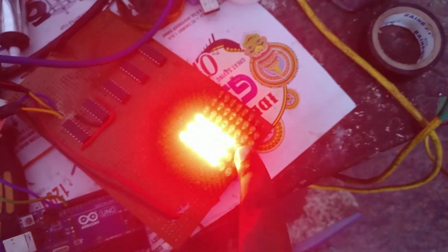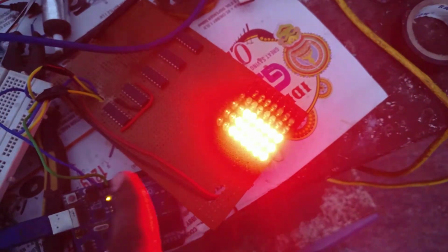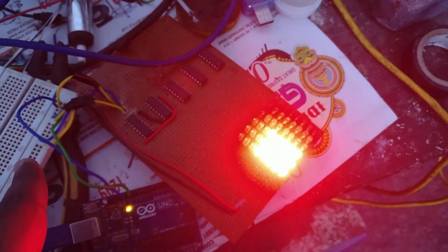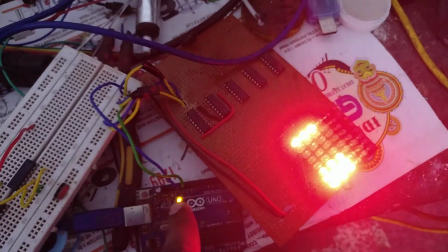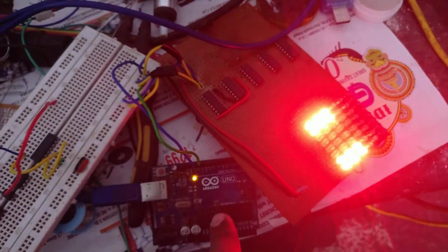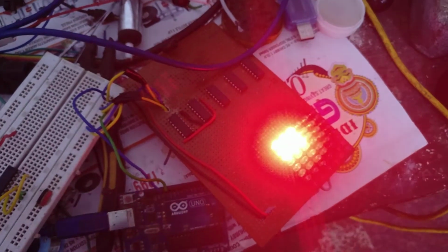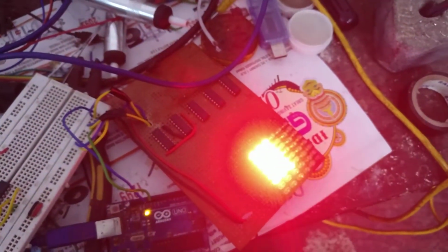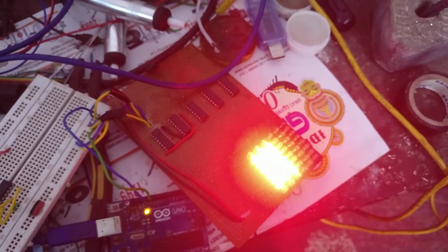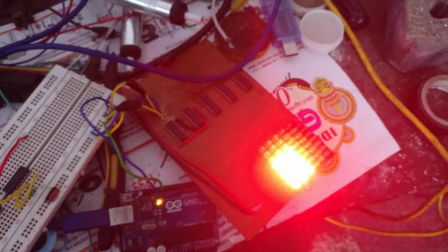What I am doing is having everything in parallel, right? All the data and clock pins are tied together using this breadboard, and it is driven by this Arduino. The Arduino is giving it a clock pulse, and sometimes the data goes slow, so it goes slow for 4 clock pulses, then it shifts. It is basically 4 clock pulses with data high, and 4 clock pulses with data low.